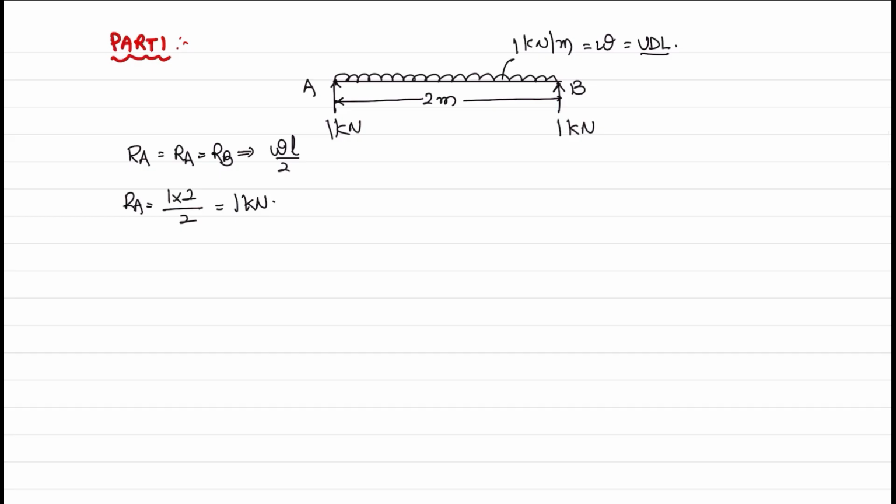This is the beam. Now, what is the shape of the bending moment diagram? BMD I have already discussed for the simply supported UDL beam, because it is the usually common beam which appears in regular engineering applications. It's positive, both sides upwards is positive. This is positive bending moment, so it will be like this.